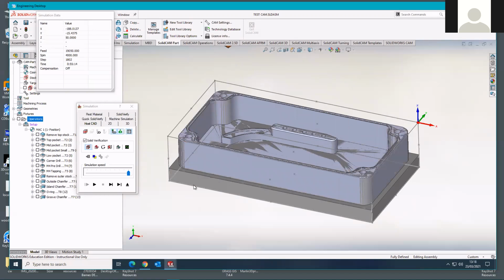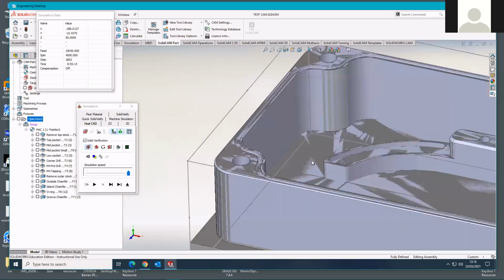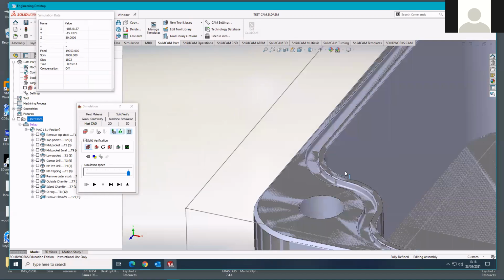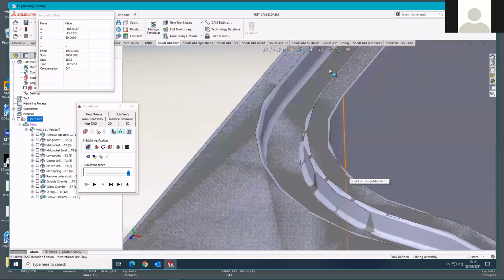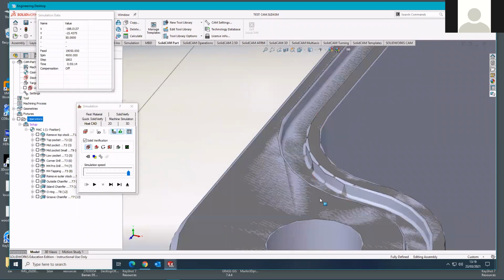there, to machine this O-ring groove for the top of the box, which if I zoom in a little bit, you'll get an appreciation of what that is. It's a little kind of trough that runs around the top of the box. And the intention there is that this box could potentially be made watertight by picking an off-the-shelf O-ring size and sizing the perimeter of this groove to the appropriate length for that O-ring, so that you could drop the O-ring into this groove and actually put a lid on this box.